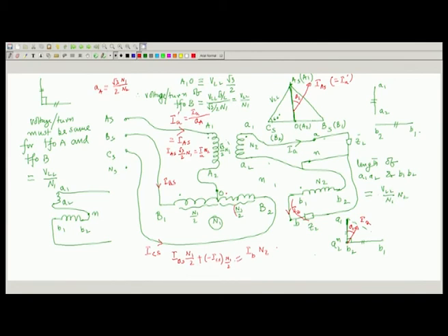See, this is crucial. See, secondary MMF through the dot I B current is coming out. I am just telling, through the dot current is coming out. So, I B into n 2, this is the direction of I B I have assumed. So, through the dot if current comes out, in its primary, through the dot current will be invited, as here was small I A through the dot, here there was no complication only, but here these two parts carrying different currents. So, I have to calculate. So, through the dot current coming out is I B.